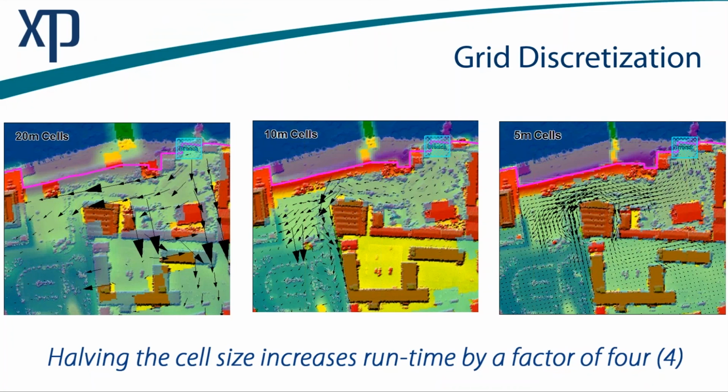One of the things that we also want to talk about today are some of the factors that go into 2D hydrodynamics. In the old way of doing hydrologic modeling, we had the catchment basin we just talked about. Now we have terrain, and we've got a computational mesh that we're going to overlay onto that terrain. One of the things that's important in that consideration is how we're going to discretize the grid, or how fine or how sparse can we make the computational grid.